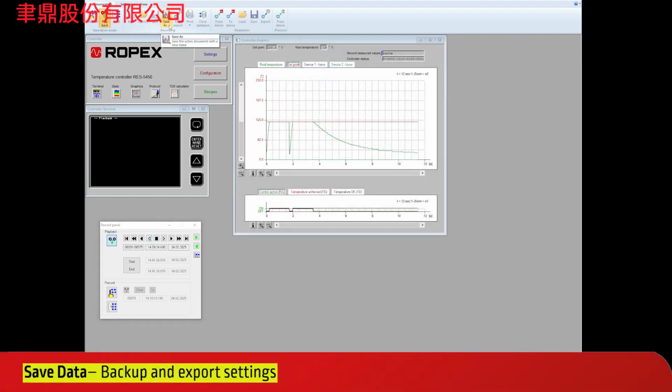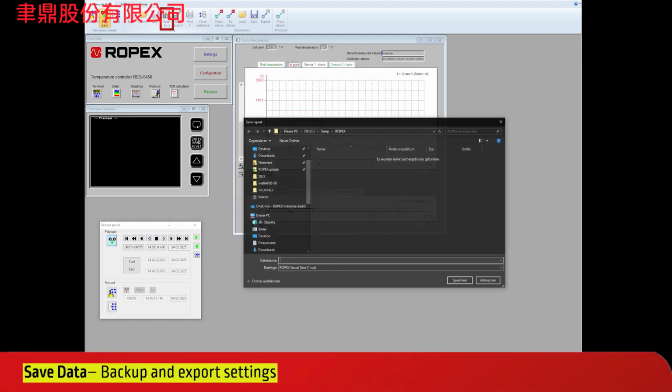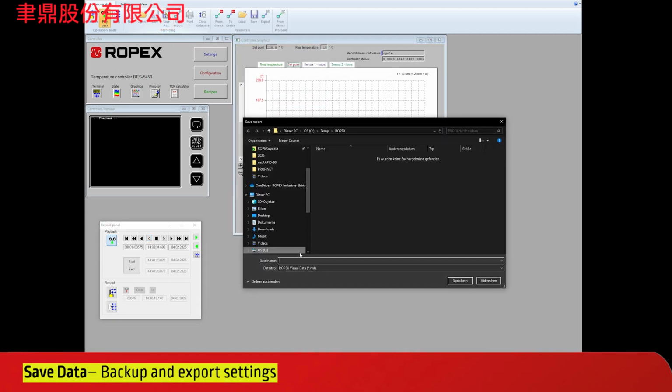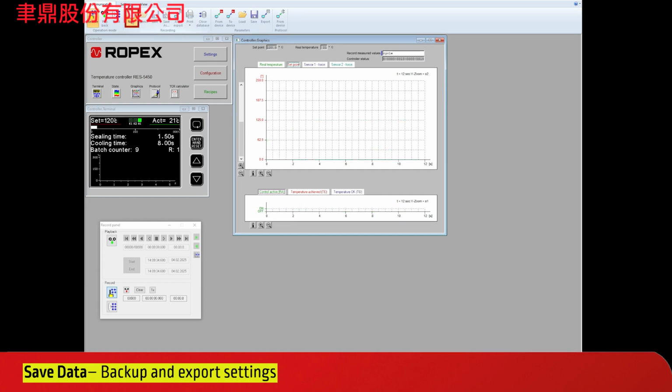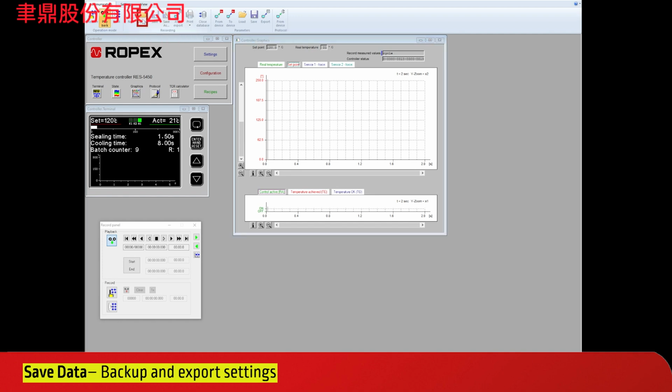Now, the process of saving and loading data is demonstrated. Graphical data is stored for future analysis and can be reused when needed. To access saved data, New must be clicked first. This clears the existing data from memory. After that, Playback mode must be activated to enable the Open button, which allows loading the selected data.